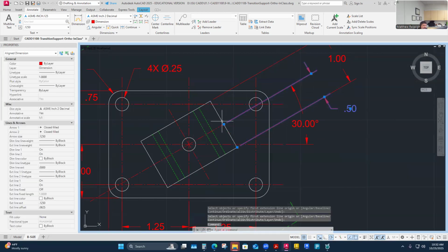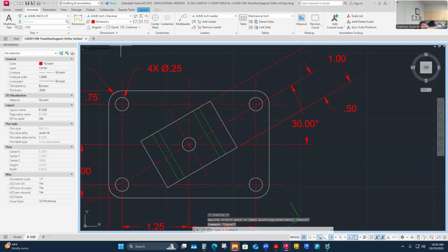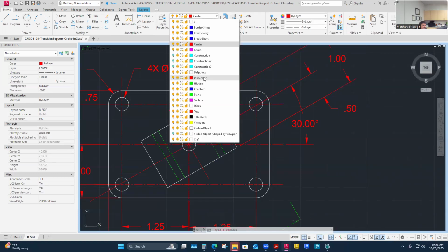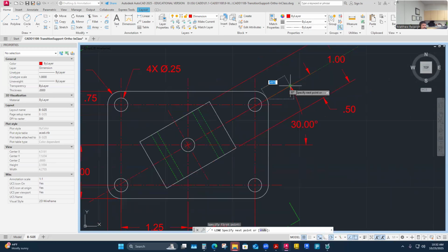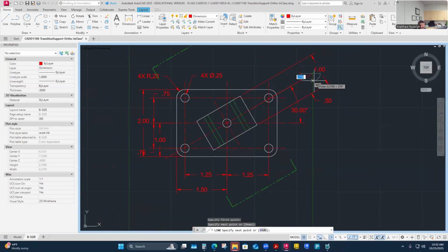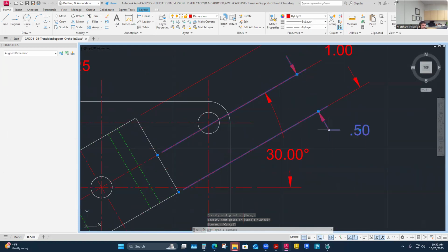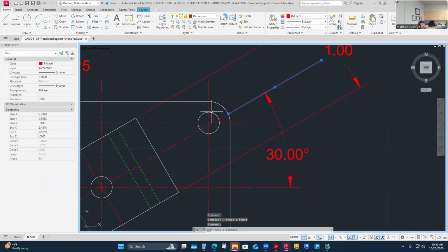I'm going to pull this one back to the object edge, which is going to be weird, right? That's going to pull weird. So I think I'll build a dimension line that's there. This is the way I got around this last time with these: I go to my dimension layer, kind of cheat my way into this. I'm going to say, oh, I want to know this dimension value somewhere out here. So I've got an overlapping line there. And now, if I just delete this for a second, I still have this dimension line to the object edge.